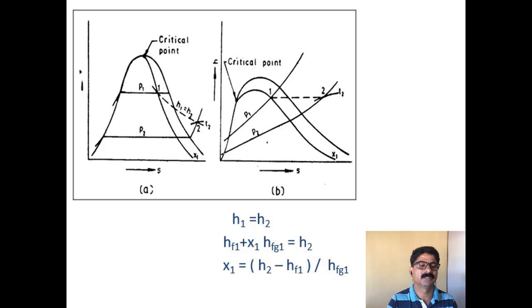This is a TS diagram. Okay, TS and HS diagram. So this is the state of the steam before throttling. That means a wet steam sample being taken at state 1, and this is the isenthalpic line. After throttling you can see the pressure and temperature marked here in the superheated region. So this is state 2, the superheated region.